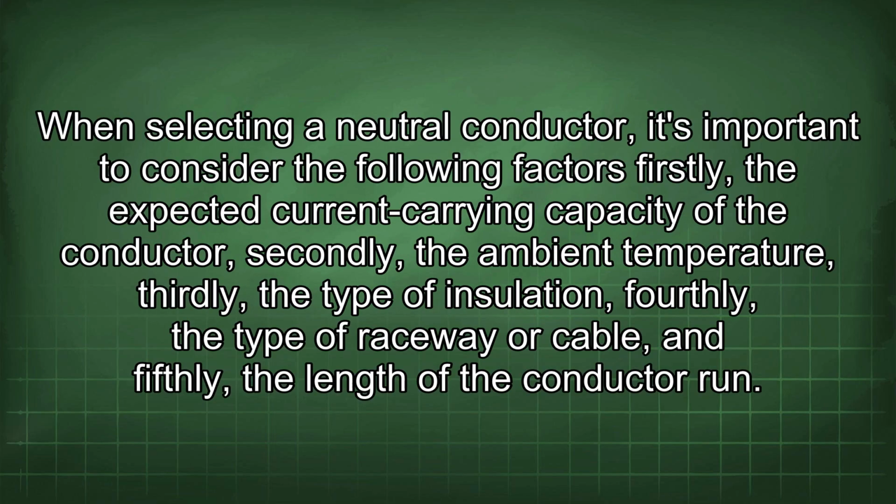When selecting a neutral conductor, it's important to consider the following factors. Firstly, the expected current carrying capacity of the conductor. Secondly, the ambient temperature. Thirdly, the type of insulation. Fourthly, the type of raceway or cable. And fifthly, the length of the conductor run.